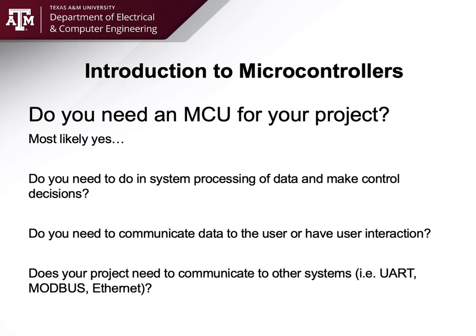It's communicating to a radio, but if it has Bluetooth, Ethernet, fill in the blank, it has a microcontroller attached to it. It might seem seamless to you because it's just sort of an additional little sensor, but if it's transmitting information, it's got an MCU. So if you're communicating data and having any type of user interaction, you're probably going to need a microcontroller.